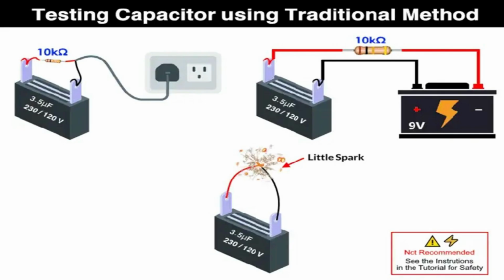Optional. Now safely connect these leads to 24 V DC or 230 VAC supply for a very short period, about 1 to 4 seconds, or for a short time where the voltage rises to 63.2% of the source voltage. Remove safety leads from the 24 V DC/230 VAC supply. Now short the capacitor terminals.